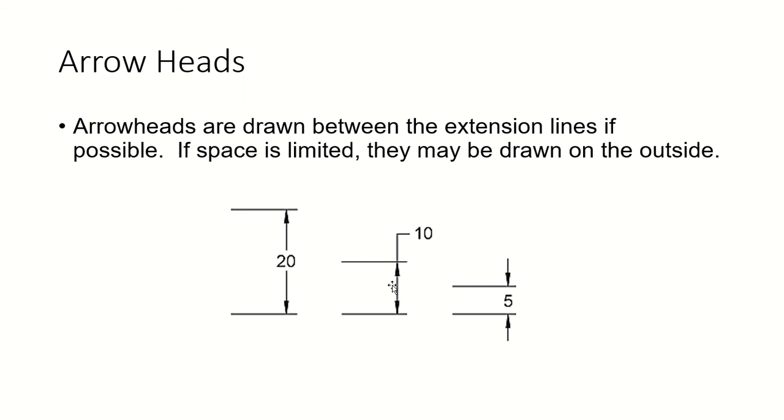And then we'll take a look at arrowheads. So you draw the arrowheads between the extension lines. Yeah, these are your extension lines. Now we draw our arrowheads in between them. If your space is limited, like for big complex drawings, you're going to put them outside.